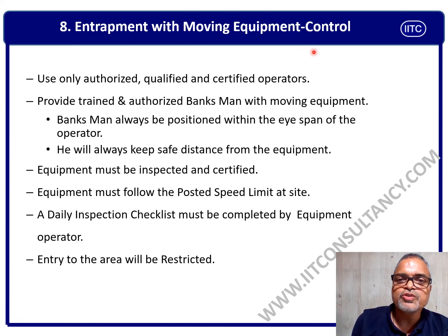Entrapment with moving equipment, there are some controls. Use only authorized, qualified, certified operators. Provide a trained and authorized banksman with moving equipment. The banksman should always be positioned within the eye span of the operator. This is a very important control measure so that vehicles cannot hit any personnel. He will also keep a safe distance from the equipment. Equipment must be inspected and certified. This is a very important point.